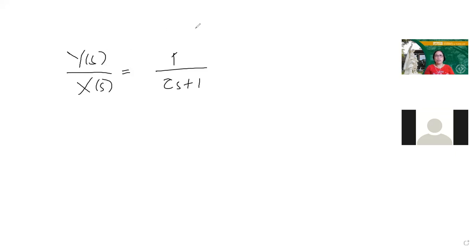So when you derive the transfer function of a first order system, this is your corresponding form. And for all first order systems that we're going to tackle, class, this will be its transfer function. You have 1 as the steady state gain because the numerator is always 1, except for one particular system. You'll know that system later. And it's always the denominator, class, that is uniform.